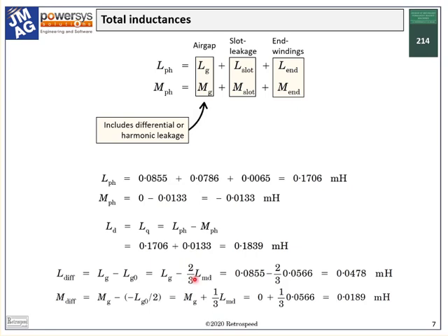That 2/3 factor appears in LMD as a 3/2 factor we saw before, and it is the only hint that LMD was effectively calculated in a synchronously rotating frame of reference by adding the contributions of the 3 phases with balanced 3-phase current. We never saw Park's transformation when we were calculating LMD, but it is implicit.